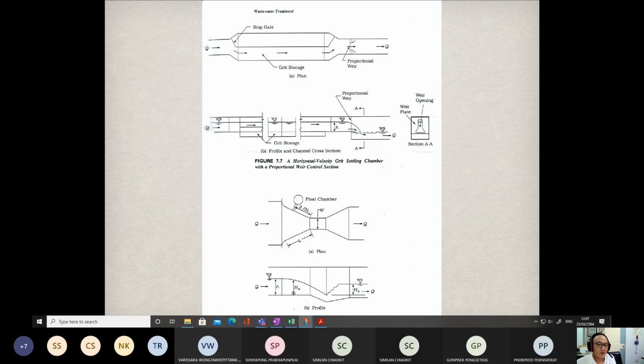And in terms of water treatment, sometimes we also add coagulants here, because mixing already occurs at this point, so that we can add alum or any form of coagulant here. In this case, we don't need the rapid mixing chamber, so we just add it here. So mixing occurs already. Okay, so this is the second beneficial use of this flume.